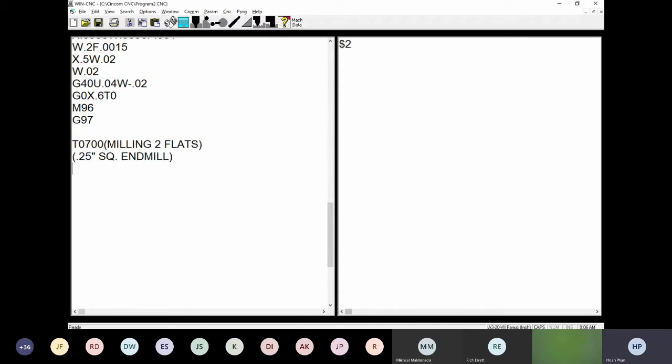Okay, right here. And then you can turn on the spindle. So the live tooling spindle is going to be S3 shift equal. Okay, you can turn on whatever you want. You need to calculate the RPM. Okay.